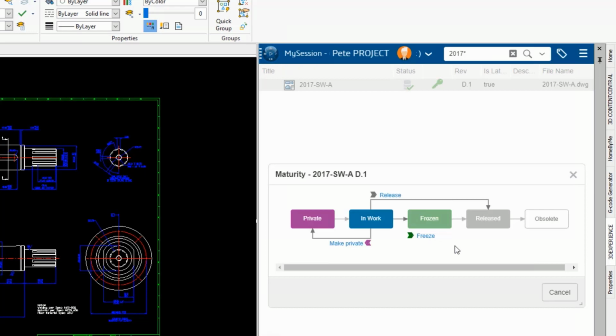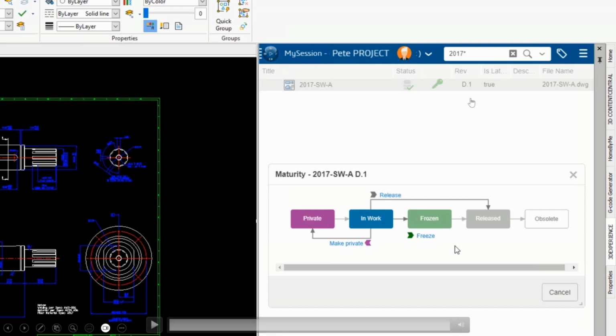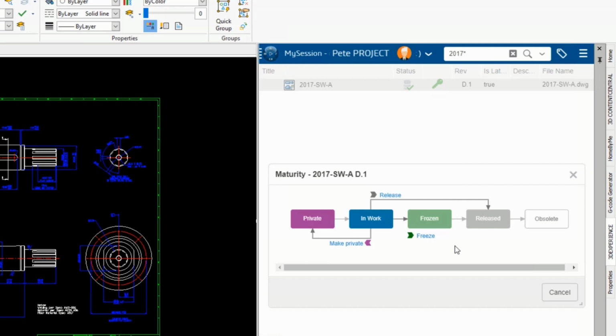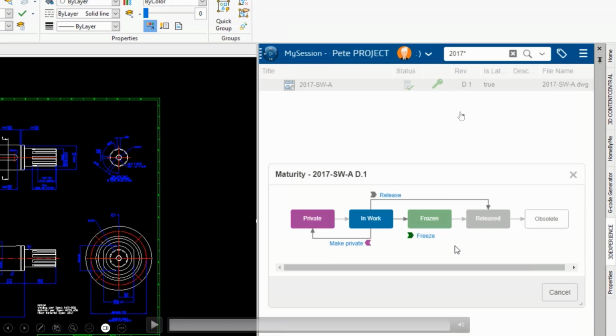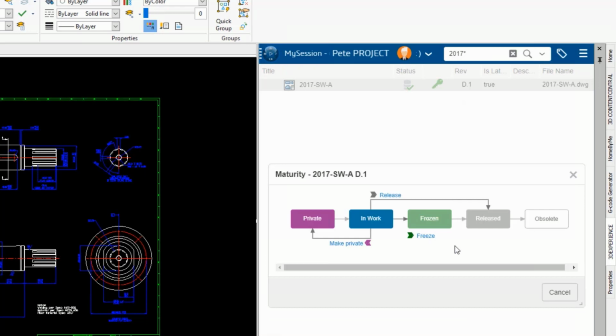And in the same kind of model, if multiple people are working in our organization, we can reserve this particular DWG file, so that when the other person tries to open it, he will be notified that another person in the organization is working on this one. And we can control its revision status. Version controlling is also available in DraftSight now. And finally, we can specify the released states, like whether it is in approval state or whether it is released for manufacturing. Those kinds of lifecycle management activities we can perform in DraftSight now.